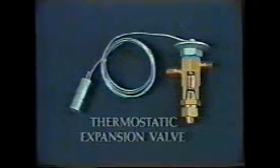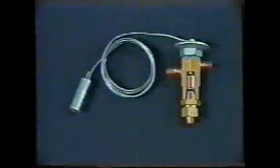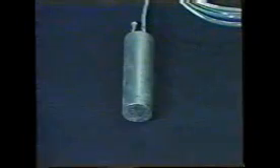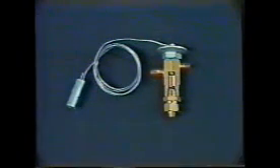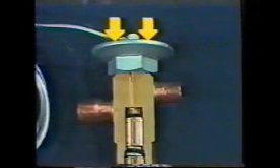Now let's take a minute to review. The thermostatic expansion valve responds directly to temperature changes. It has a thermal sensing bulb that is mounted on the suction line to the compressor at the evaporator outlet. The bulb senses the temperature of superheated vapor leaving the evaporator. If the degree of superheat of the vapor is too high, the valve will open to let more refrigerant into the evaporator. If the degree of superheat is too low, the valve will close to reduce flow into the evaporator.